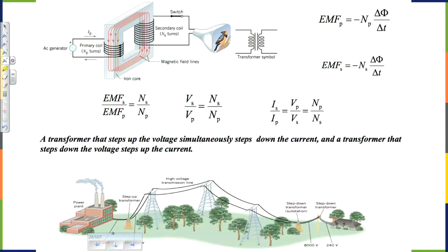Unfortunately, a lot of energy is getting lost to heat, because even if the current is small, wires are very long. So if you remember, Q equals I squared times resistance. So ideally, it would have been nice to have wires with no resistance. And in 1986, high temperature superconductors were found. But unfortunately, those materials are ceramics. You can't make a wire from ceramics. So far, we still use mostly copper wires.